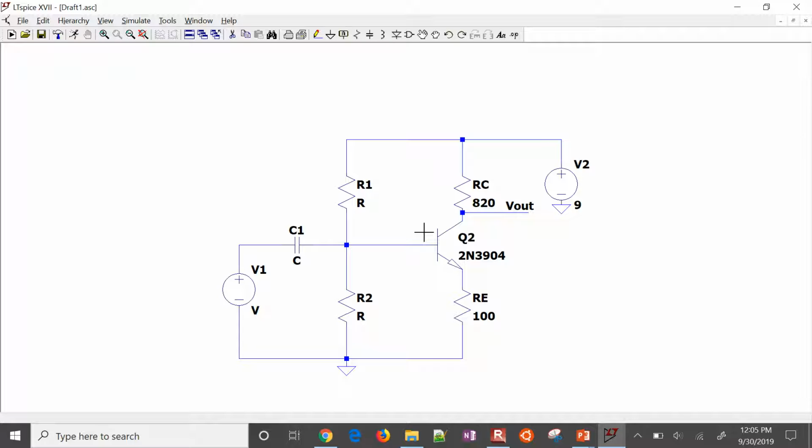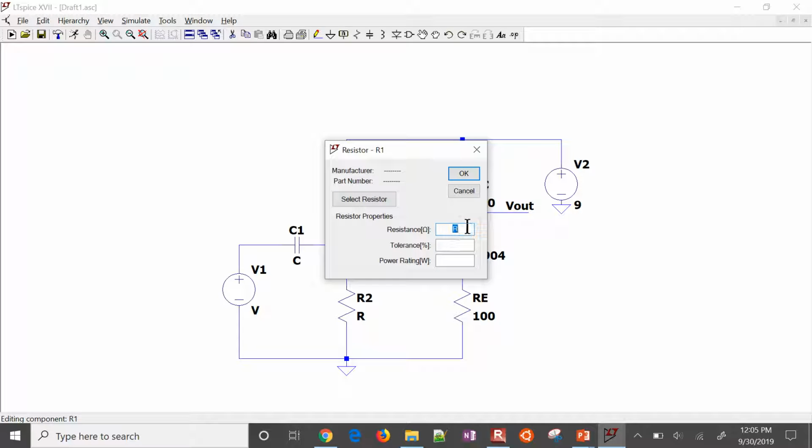So we're going to pick a value for one and then solve for the other. So I'm going to pick a value for R1, especially when you get to Lab 5 on your PCB. There's 1 slot for R1, and then there's 2 slots for R2. So if you pick R1 to be something that's a standard value, then it makes it easier. So I'm just going to say 12K. I could say 10K. I could say whatever I want. I could say 8K.